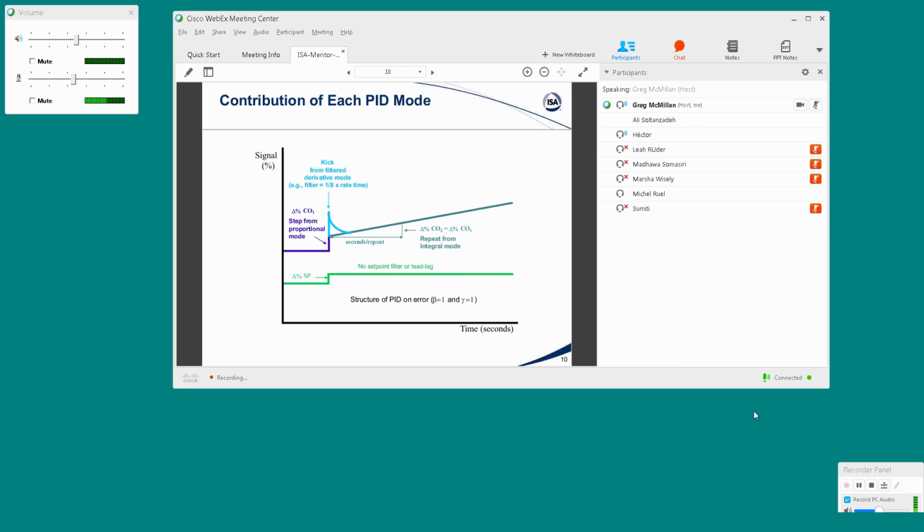The other method, of course, originated from Ziegler-Nichols, but I've modified it in saying you never really want to go for ultimate oscillations. You just want to get some oscillations, and then you measure the period to get an idea of what the reset time is. You're probably going to end up with a larger reset time, but that's probably good, and then you cut the gain more and you test it again. But then there's another method, and people can keep the controller in automatic and make a set point change. If the tuning is such that it has a lot of proportional action, I can develop a calculation that will identify it. But I'm sure there's software out there that can identify the dynamics from set point changes.